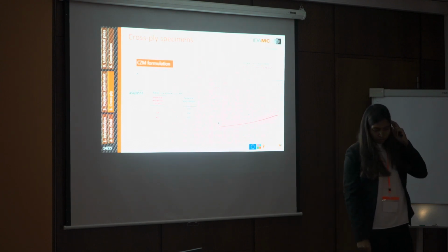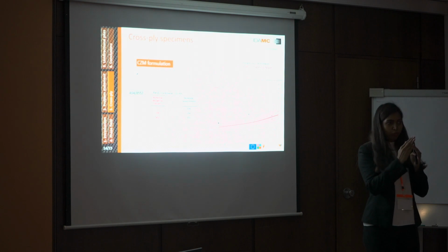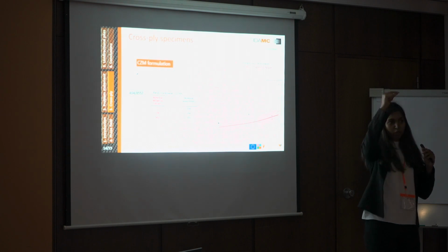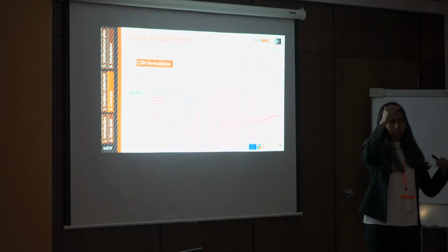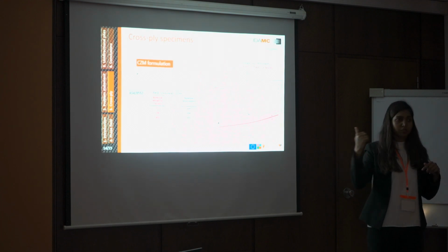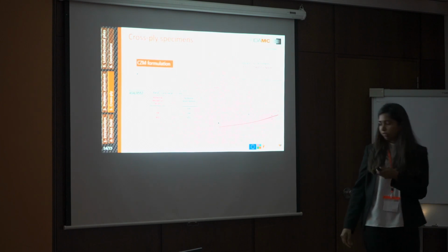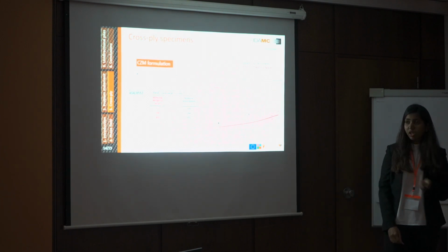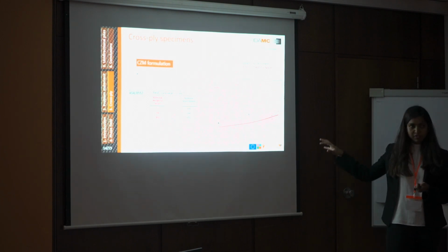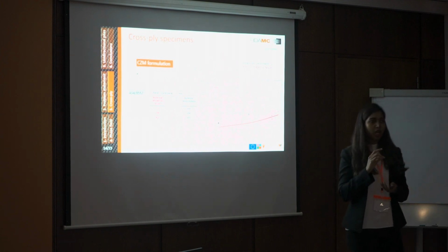So in conclusion, for the AT1 and AT2, we have very good correlation with the failure moment values, but not with the initiation. Whereas for the CZM formulation, we have good correlation with the initiation, not with the final failure moment values. That is because in the phase field formulation, in this presentation, we haven't taken into account the impact